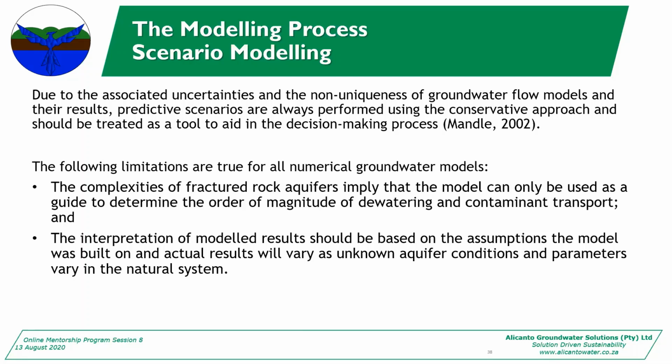If I've got huge variations in data sets, I'll calibrate my model, but I'll also say, if my recharge is half of what it is now, like in a drought scenario, this would be the impact. If we have a huge fault zone that we can't prove, but it might be there, this would be the impact. So we choose our scenarios based on the application.